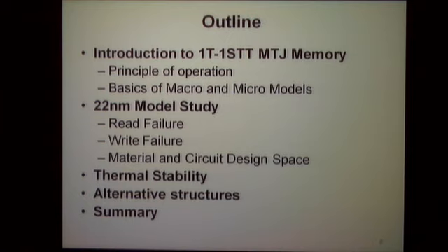And I'll talk about the different kinds of failure mechanisms, which will, I think, answer one of the questions from the first talk. What are the different kinds of failure mechanisms we can think about in these kinds of structures? And again, looking at it from an embedded memory perspective. And finally, I'll talk about some of the issues with thermal stability, since we are looking at extremely small dimensions, and look at some alternative structures and what the problems and potential solutions are. There are no solutions for many of the problems as of yet, so I'll talk about those as well.